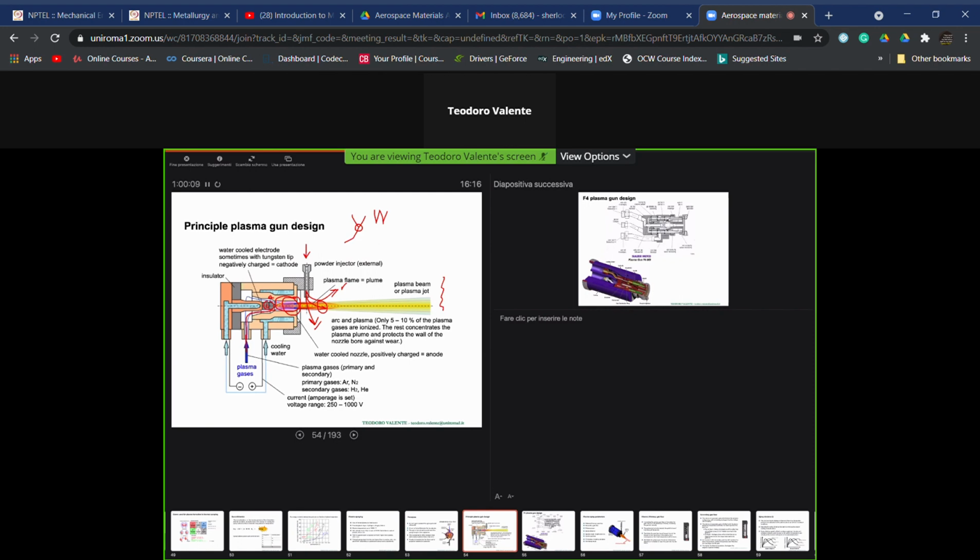And even though the melting temperature of copper is not so high like that of tungsten, the cooling system can be designed in a very efficient way. That's an engineering problem in order to avoid melting of copper. And so the spare part of this torch is essentially the cathode of tungsten, instead the part of copper, which represents the anode, works for the whole lifetime of the torch itself.